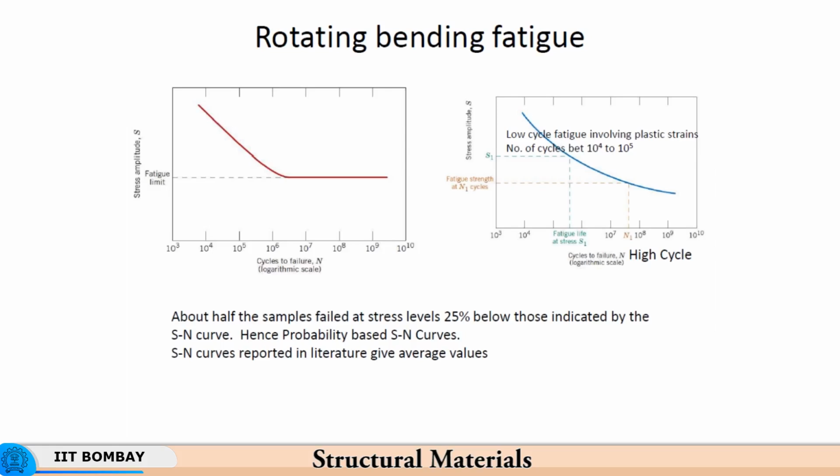Now, if the loading is very light, because loading is the driving force for the strain energy to get generated, and this driving force is relatively small as you reduce the load, then there is just not enough stress, not enough strain energy for the crack to propagate. Naturally, the crack will remain at the same size and will be there forever, because at no point is the strain energy going to exceed the surface energy that is needed for propagation of the crack.